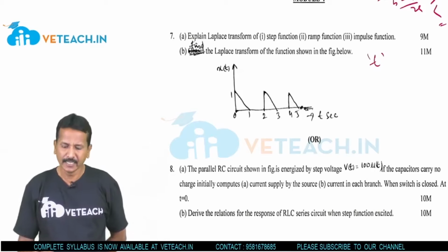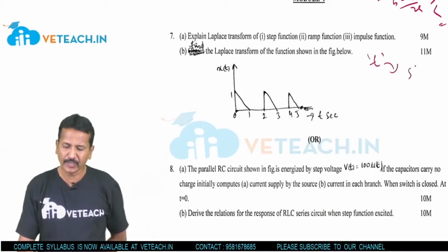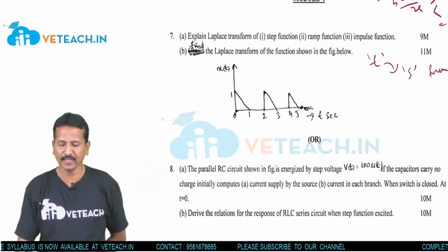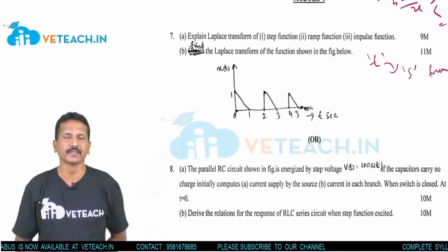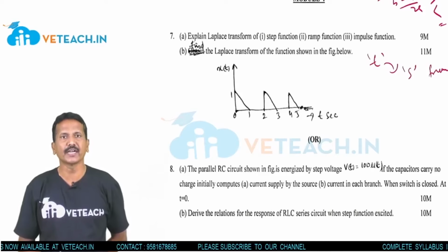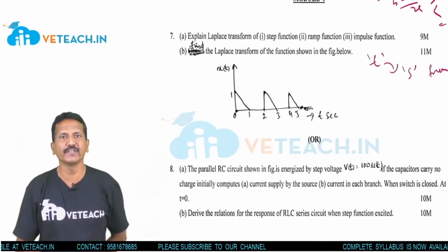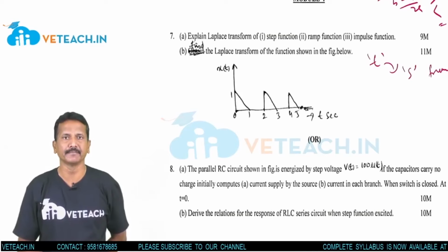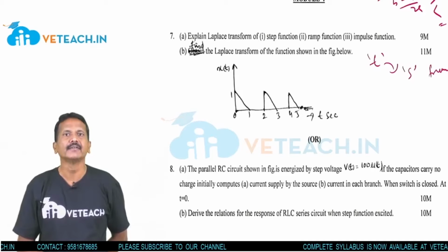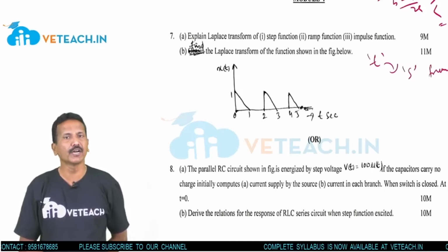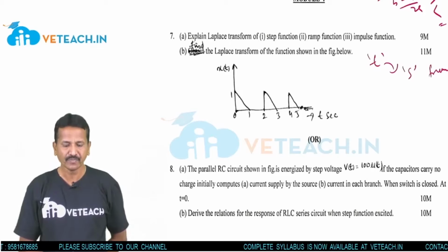For that purpose, the time domain can be converted into the S domain, that is the frequency domain or angular frequency domain. So the Laplace transform is nothing but where the time domain is converted into the frequency domain or S domain. In the S domain, we can identify very easily whether the system is stable, unstable, critically stable, or overstable.